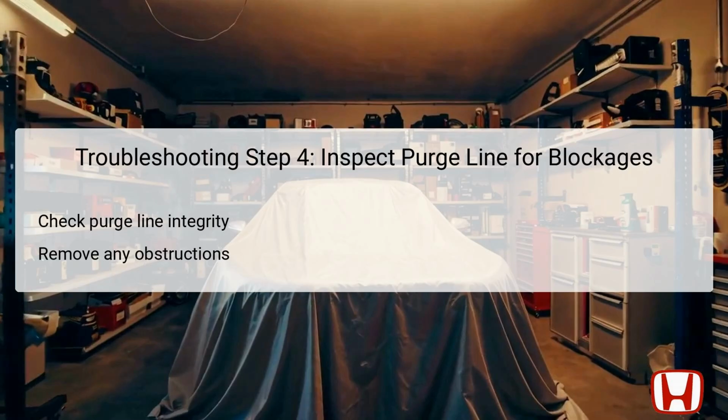Look for signs of kinks, cracks, or other damages that may restrict the flow of vapors, compromising the efficacy of the entire emissions system. If a blockage is detected, such as dirt or a foreign object, it should be carefully removed to restore normal function. Addressing any integrity issues with the purge line is critical for ensuring that the vapor purging process occurs smoothly. This step is vital for maintaining a properly functioning evaporative emission system.